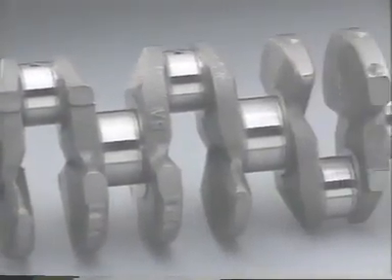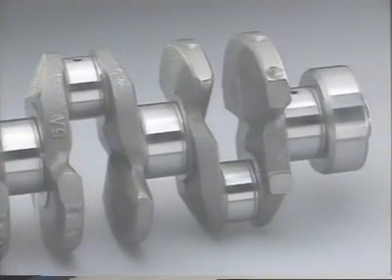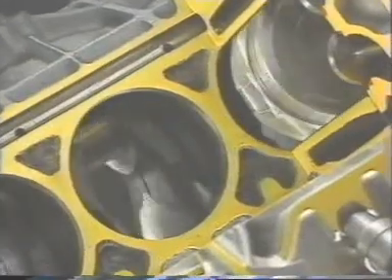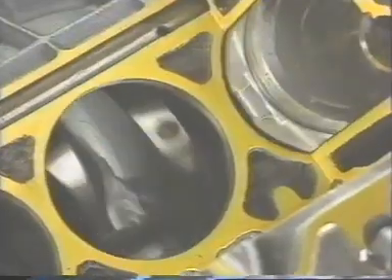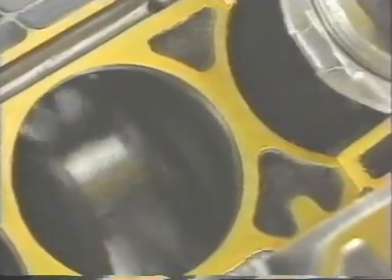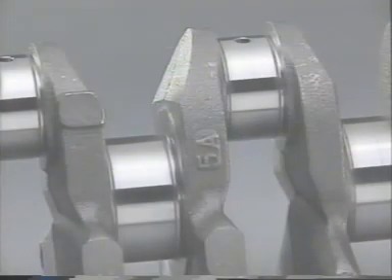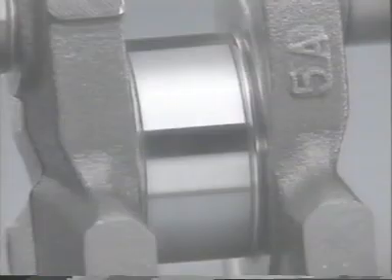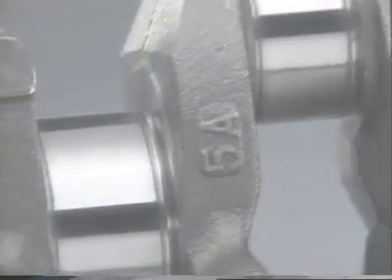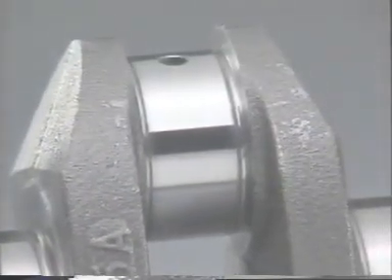The crankshaft rotates at high speed under the heavy load applied by the pistons. It must therefore be sufficiently strong and rigid and well-balanced both statically and dynamically. To meet these requirements, the surface of each crank journal and crank pin is hardened to a depth of 2 to 3 millimeters for high wear resistance and toughness.